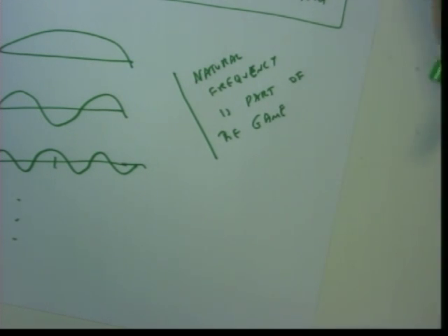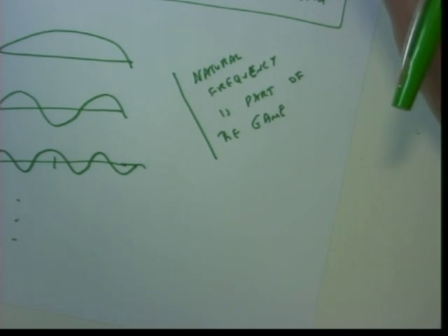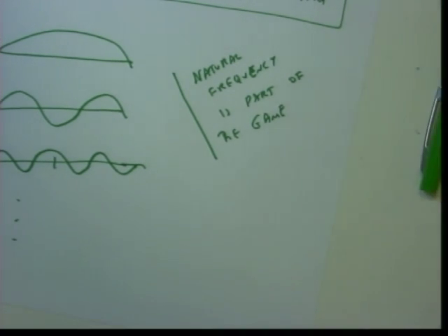That is why we studied and will study a lot of natural frequencies for forced excitation. Again, why do I need natural frequencies? My ultimate goal is not natural frequencies, but my ultimate goal is response. In order to find the response, we need natural frequencies.